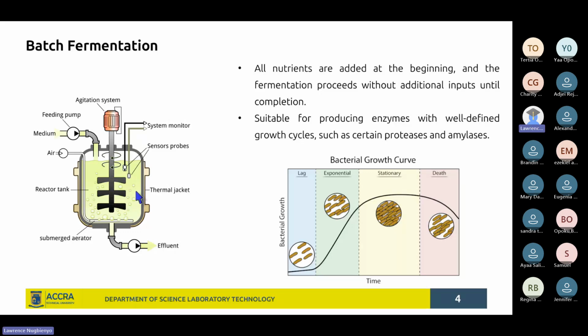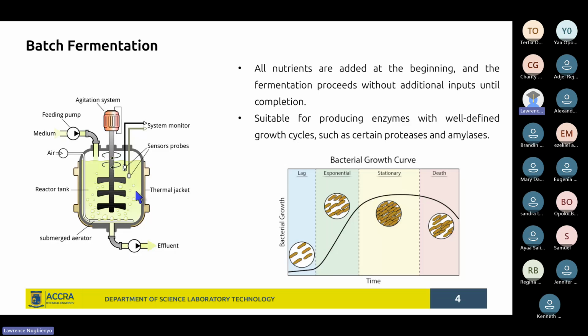You will see these parameters on the monitor. And if, for instance, too much pressure is building up in the bioprocessor, there should also be a sensor for sensing pressure. It will quickly give an alarm, maybe some sound or light beeping, to call your attention so that you can attend to such a problem.